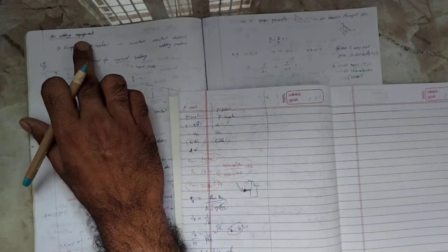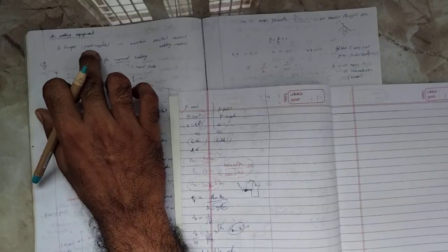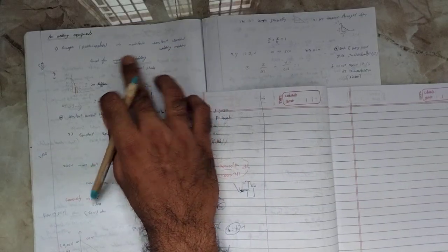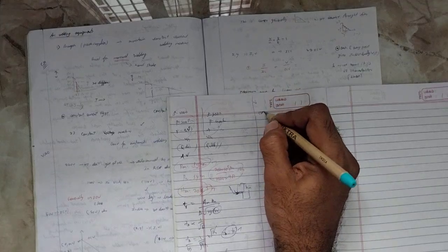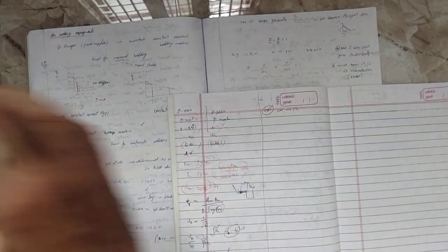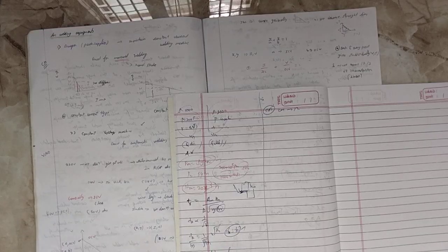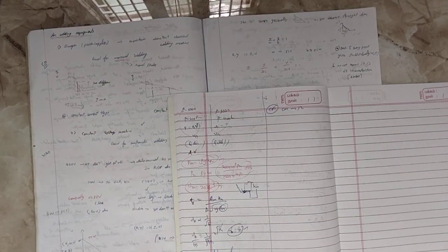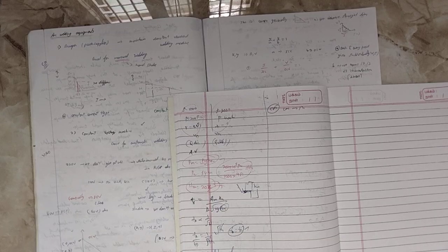So you can see this one, arc welding equipment. First one, a drooper power supply to maintain constant current in the welding machine, good for manual welding. Constant current is generally used for manual welding. Why manual? Because sometimes the hand may shake, so due to a little bit of extra problems, this kind of manual welding is used.